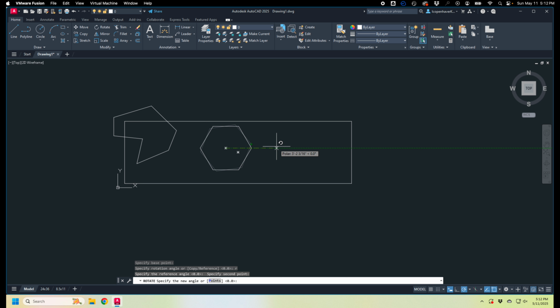much, much easier to control, and I can use some of the polar tracking which we haven't talked about yet, to lock into place, or I can type in a number. That brings up polar tracking. So let's introduce ourselves to this button down here. Polar tracking restricts your cursor to specified angles. Sort of. So when you're close to something, it just means it's going to snap to it.